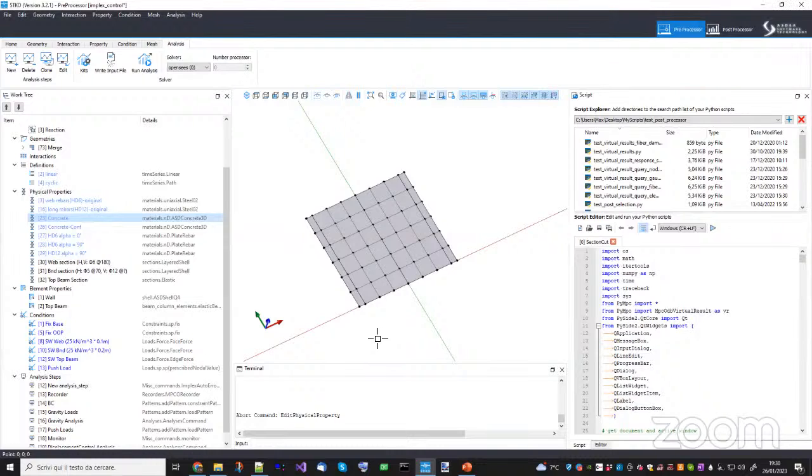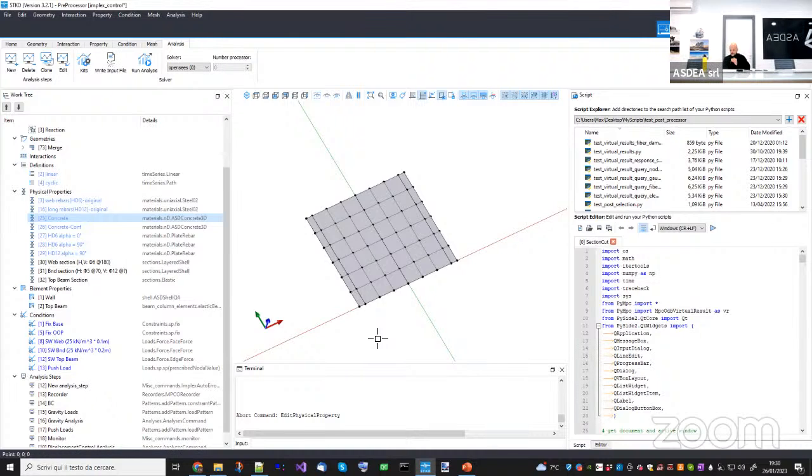The reason is that the transformation handler is changing the number of equations. So it may happen for some reason, and I still have to debug it. When you have the same constraint in some partition, you may have a different number of equations, and it doesn't match the equations on the other partition. So sometimes it may happen. So a typical rule would be: if you have multi-point constraints and you experience problems like that in OpenSeesMP, just switch to the penalty constraint handler. Okay. I see.